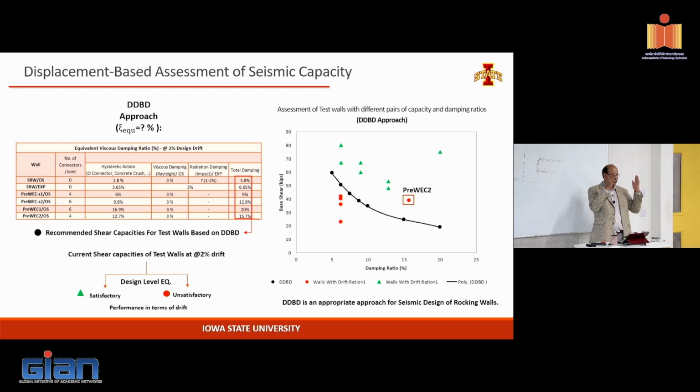They are full length. So the precaster can choose to cut the wall in 2 panels, if you like, right? If it's a 6-story, they may bring the wall in 2 or 3 segments. Between the walls, there's a concept people use in the precast world: when you establish a connection, is the connection going to be stronger than the member or weaker than the member?